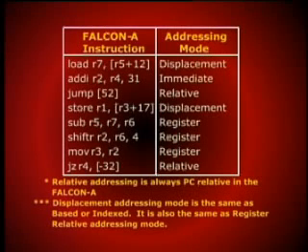Add immediate has immediate addressing mode. Jump has PC relative addressing mode. Again, store is a displacement mode, and next three instructions, subtract, shift right, and move, only involve registers, and therefore these are register addressing modes. And the last, jump on 0 instruction has a relative addressing mode. As indicated in the previous lecture, the relative addressing mode is always PC relative in the Falcon A. Displacement addressing mode is the same as based or indexed. It is also the same as register relative addressing mode.